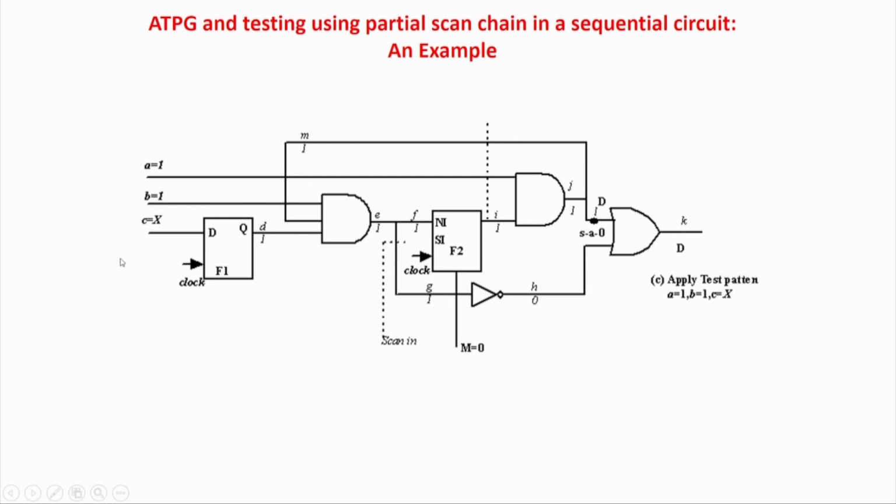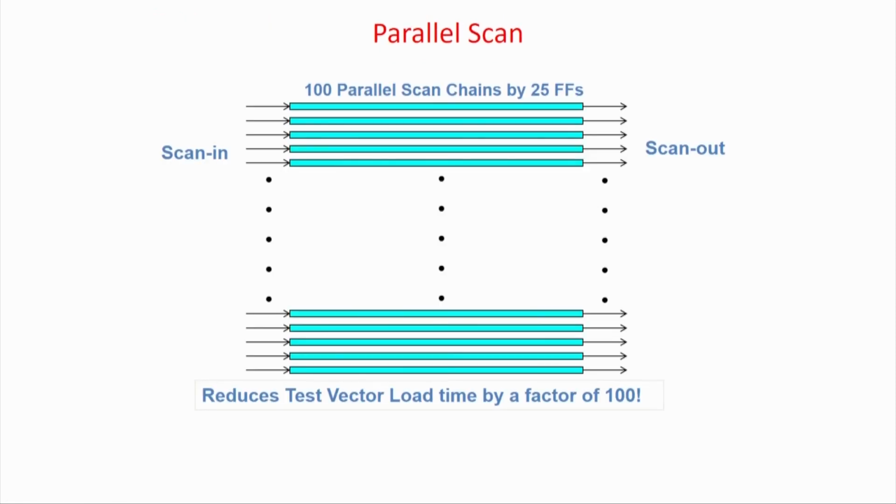The advantage of this pattern is that this flop is not scan enabled, so you are saving on the multiplexing cost, and this one had to be made scan enabled because it is a cyclic flop. Also F2 could have been a flip flop which is very far down the line of depth, some 10,000 to 20,000, then the same approach which we will do. So basically that is the idea.